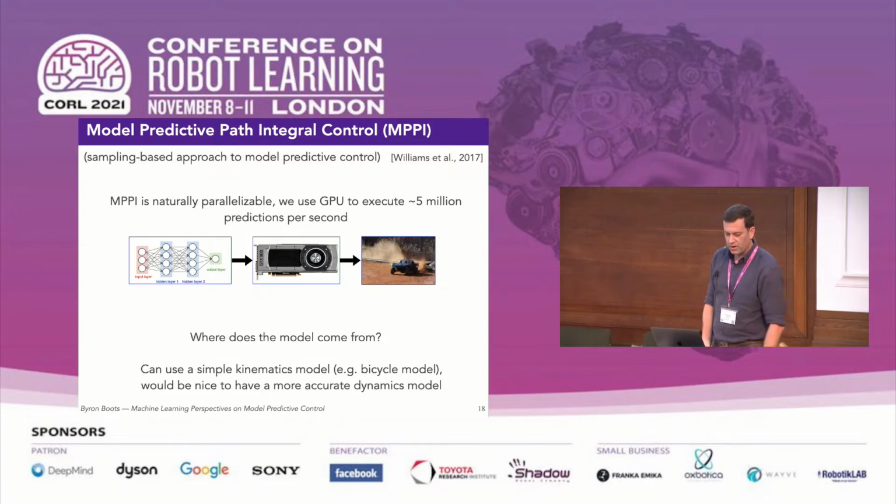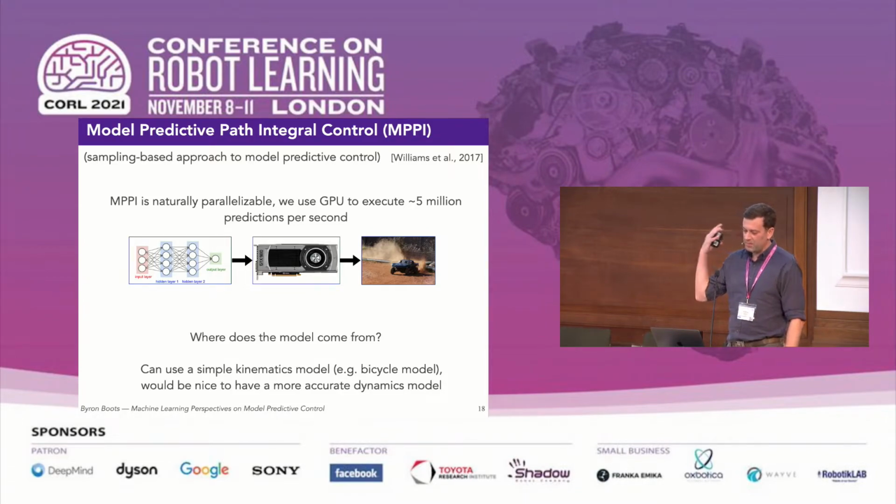All right. So MPPI can actually be really, really fast if you implement it on a GPU. Sampling trajectories is, if you think about it, a naturally parallel task. And so we can sample huge numbers of trajectories in real time on a GPU. For our robots, we can sample literally thousands of trajectories at 50 hertz or higher when we're trying to complete these tasks.